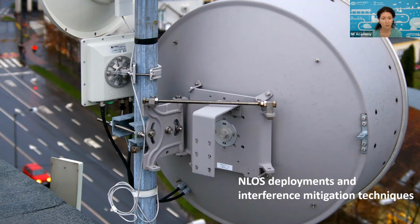What is the minimum separation distance required between collocated devices to avoid performance degradation? As I said during our webinar, it is 2 meters between the edges of the antenna. This is the recommended situation. You can try lower values, but only if you do the tests for interference and decide that it is fine. But the recommendation is 2 meters between antennas.